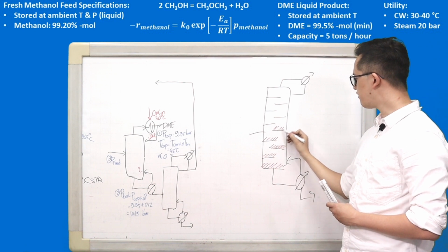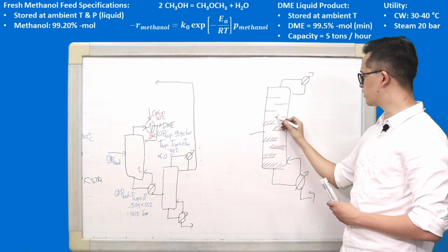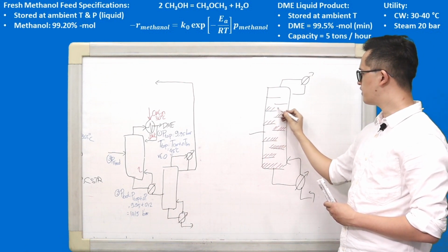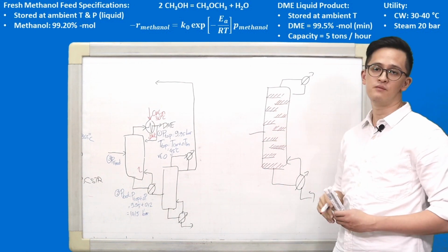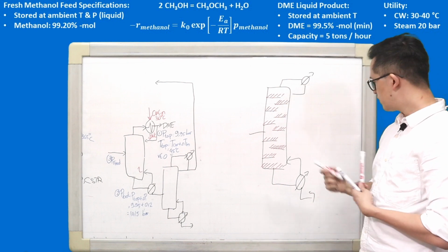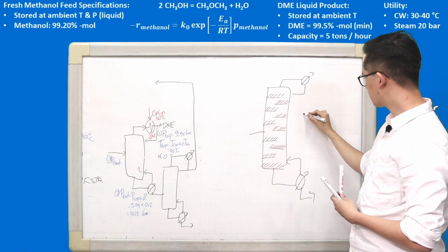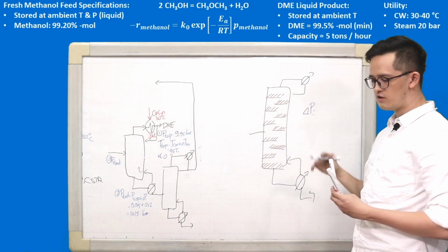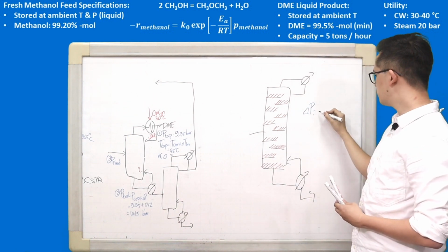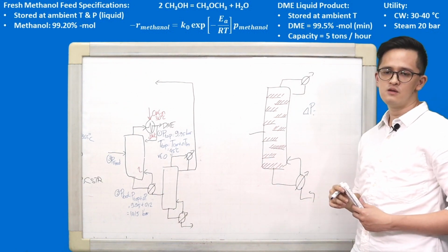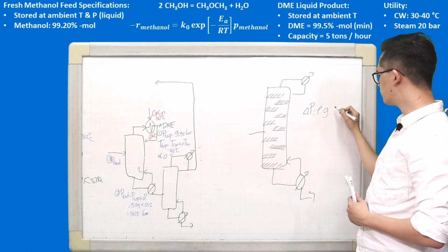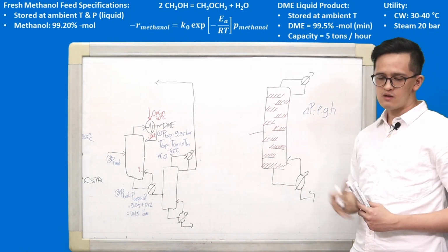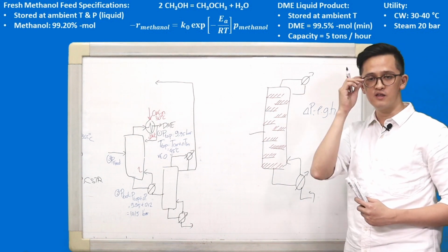And if we have the accumulation of those liquid holdups, we will have a hydrodynamic pressure inside of the column. Actually, the easiest way to calculate the pressure drop is by calculating the hydrodynamic pressure. It's the density times the gravity constant times the accumulation of the liquid holdup.